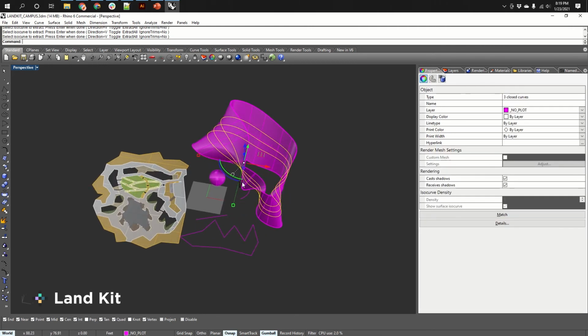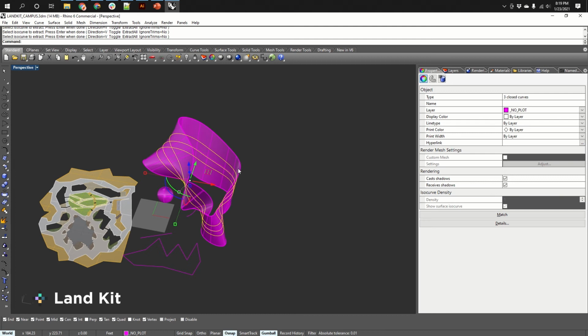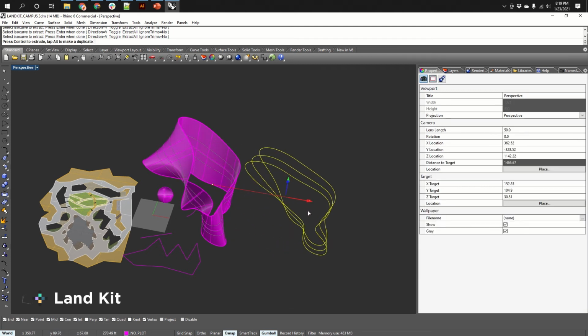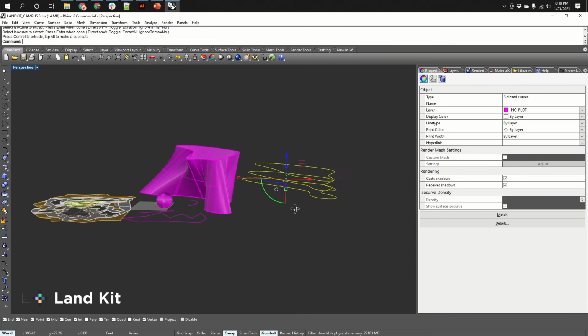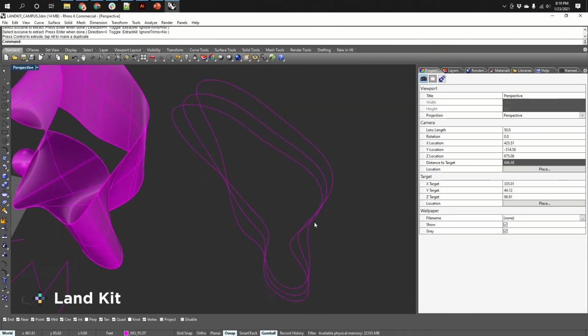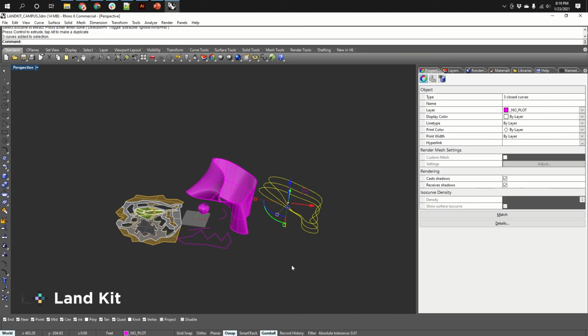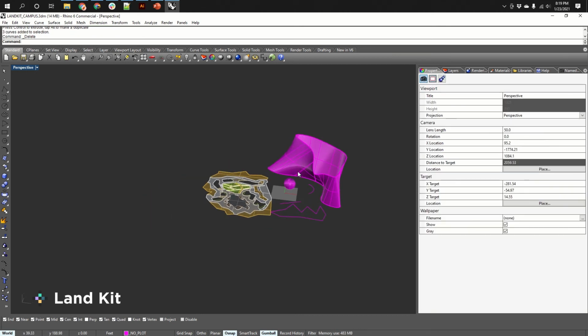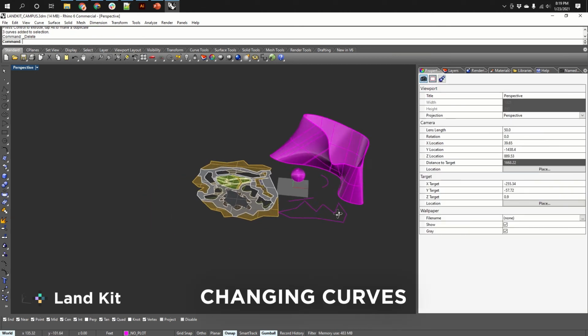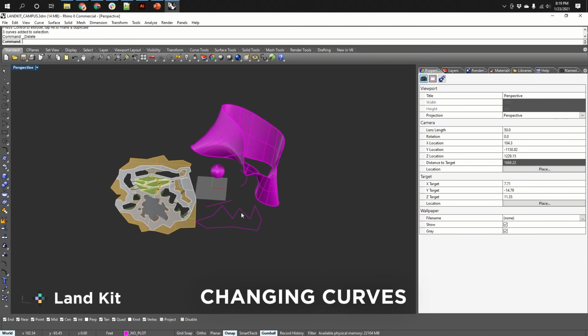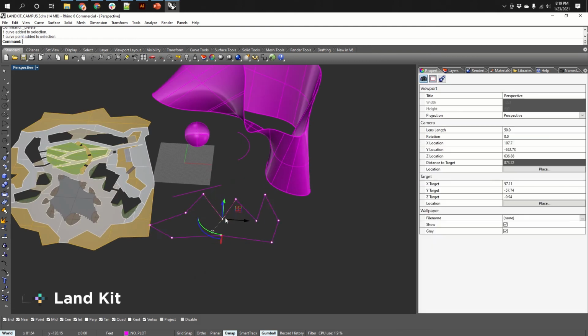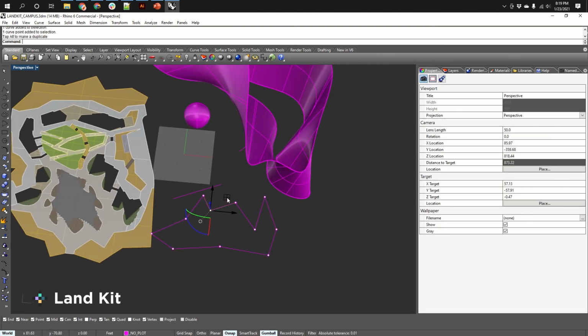everything that you select is in yellow, as you can see, and these are selected automatically after I create them. I'll move these over with the gumball here, and now I have some curves that are taken from this surface. Pretty interesting. Now, we can manipulate these geometries in different ways. If it's a curve, you can grab a point and you can move that point around. This red and yellow square is the XY.